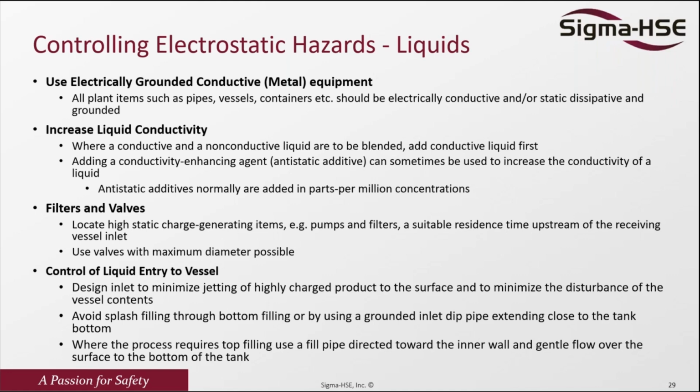So how do we control the hazard associated with liquid? The first one is to use electrically grounded metal equipment. That is very, very important.